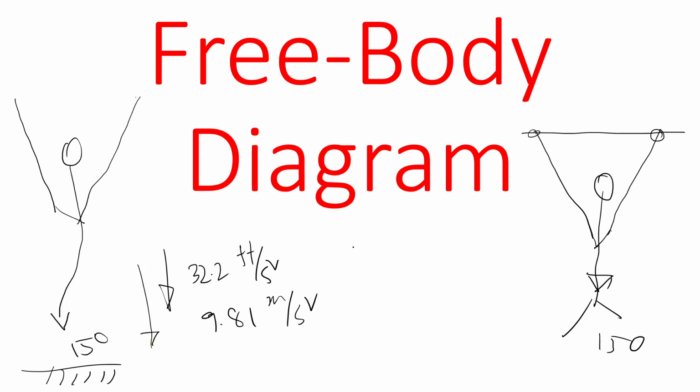Now remember, everything is static here, so you are making an imbalance by freeing the body. So you have to balance it now by applying some opposite forces and moments, whatever is applicable. In this case, it is the tension in my hands that will balance me. So the concept of free body: first you free the body. So we free the body right here.